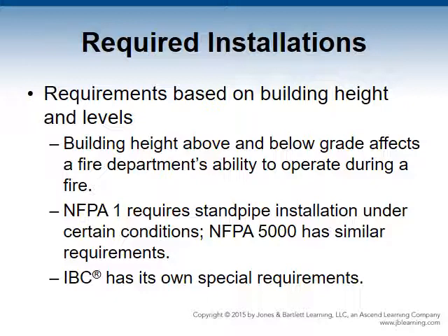The IBC states that a standpipe is required if the vertical travel distance inside any part of the building is more than 30 feet above or below the fire apparatus access level.